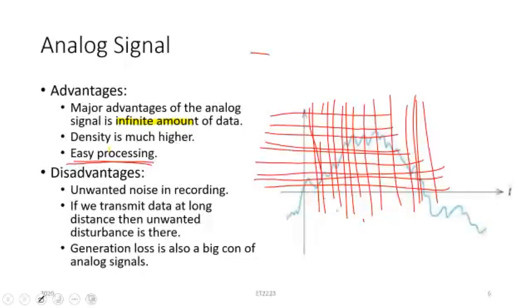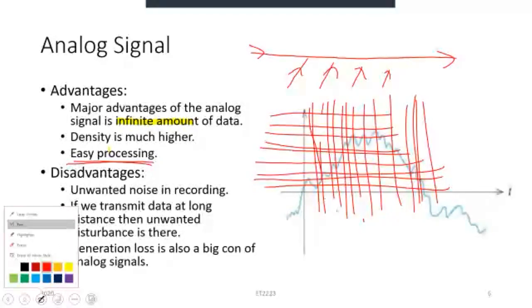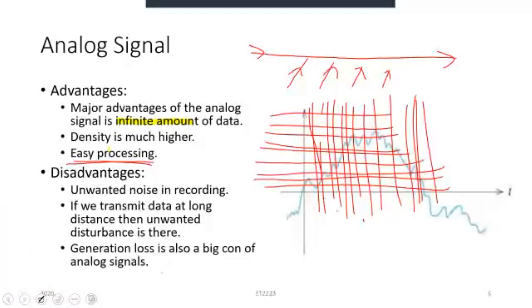So we have audio signals being carried through a wire, and if there is external magnetic interference, for example, this analog signal would be significantly affected. The longer that we transmit this, the more it is going to be impacted by noise. If we are fairly close, the impact would be less. If we are traveling much further, the impact would be much more.